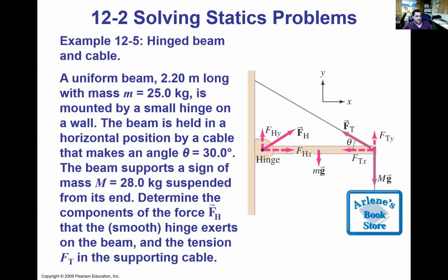So to summarize, I summed my torques about this end to make some of those lever arms zero. I resolved this tension in the Y and tension in the X to get the total tension. Okay.